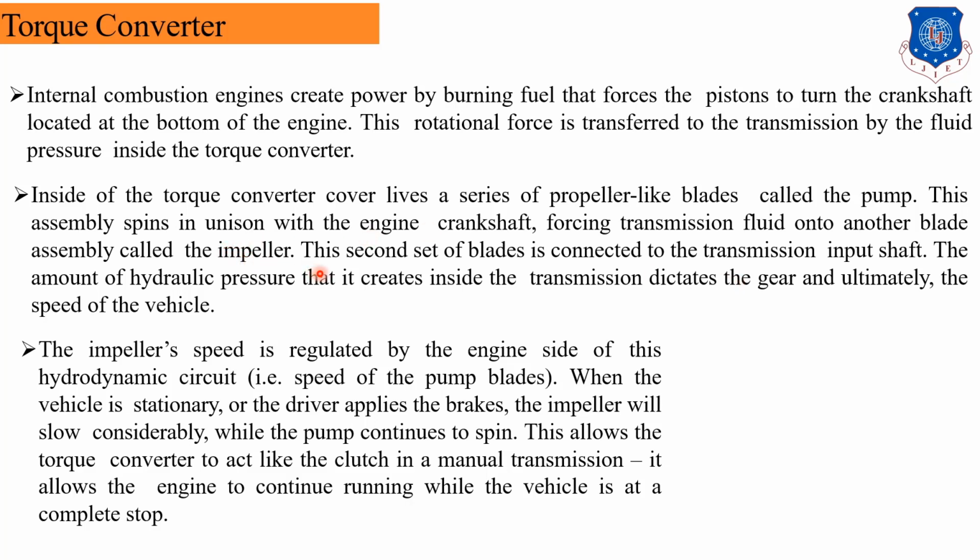This second set of blades is connected to the transmission input shaft. The amount of hydraulic pressure that it creates inside the transmission dictates the gear and ultimately the speed of the vehicle. The impeller's speed is regulated by the engine side of the hydrodynamic circuit, that is, the speed of the pump blade.